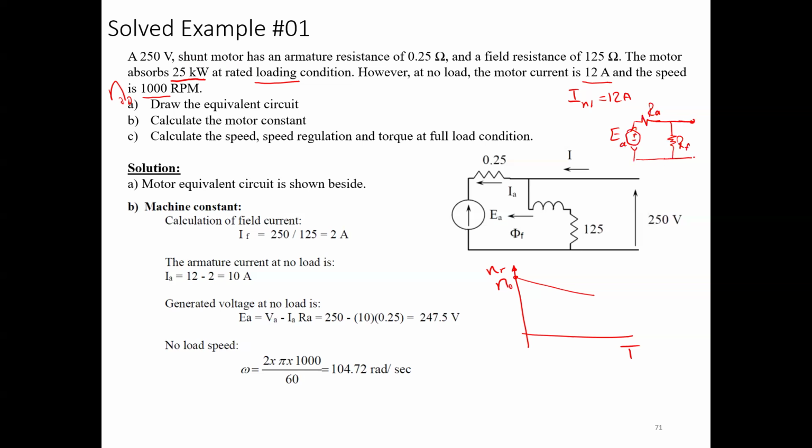And by the end, these are the terminals. So this is V terminal here, and this is I input to the motor. This is here I field, and this is the armature current. So this is the schematic. This is the textbook drawing, and you can make it easier like that if you don't need to make the inductance in parallel or 90 degrees like that, and the resistance in parallel like that. Okay, so this is part A.